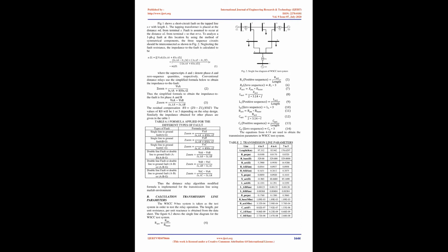The WSCC 9-bus test system IEEE benchmark model which is used in the project contains 3 synchronous machines with built-in voltage and speed regulators, 3 two-winding transformers, 6 constant parameter lines and 3 loads. Algorithm for distance relay in tapped transmission line.